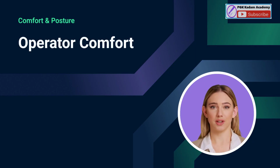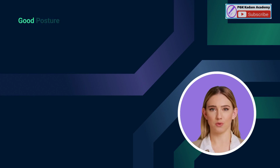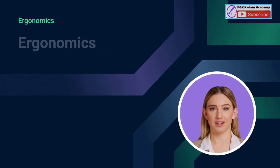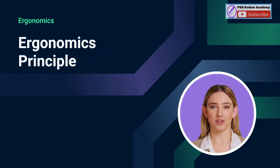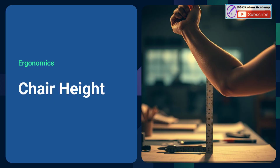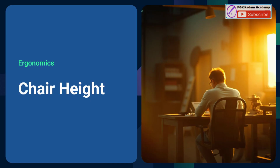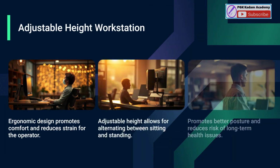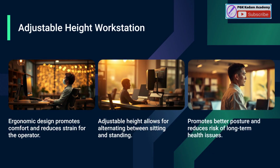Operator comfort and posture. Posture of the operator should be comfortable. Extreme movements must be avoided. Under ergonomic seating, the chair or stand should be as per ergonomic principles. The height of the chair should be such that the top of the work table is about 50 millimeters below the elbow level of the operator. The height of the table should be such that the operator can work in both standing and sitting positions.